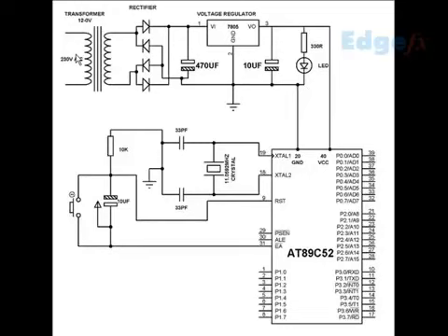If it is to be operated directly from the battery, we do not need the supply, as the microcontroller needs 5 volt. What we do is take a 6 volt battery and connect a diode in series, which solves the purpose of supplying 5 volt to the microcontroller at pin 40, and pin 20 is always negative. The other connections are very standard.